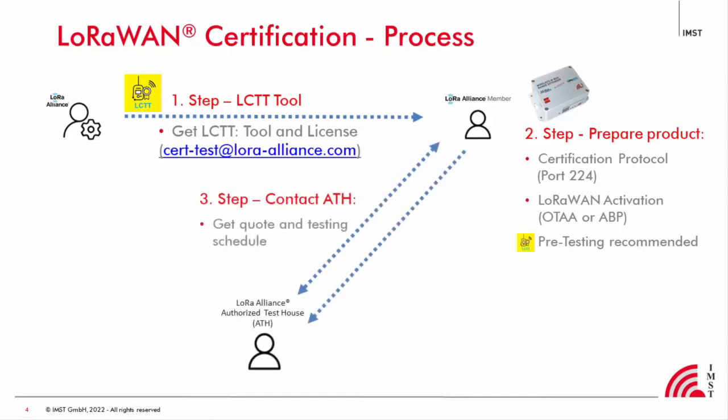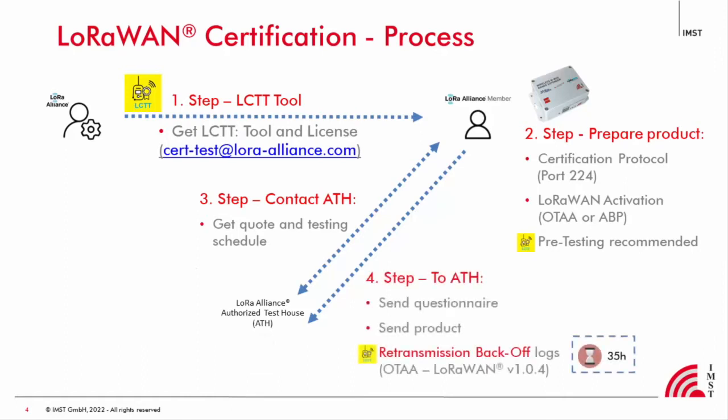After that, you should contact the LoRa Alliance authorized test house. They will send you a quote and a questionnaire, which you need to complete with information of your end device. You could also arrange a testing schedule. Once you have your product ready, you have to send it to the test house. And don't forget the retransmission spec of testing for LoRaWAN version 1.04.